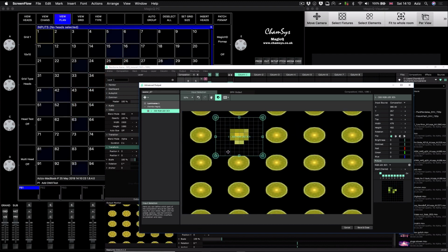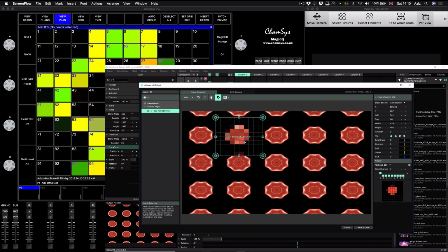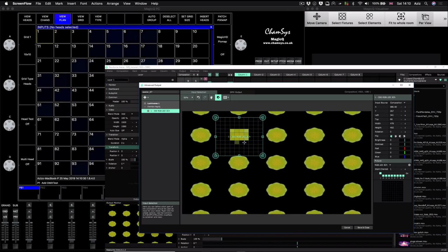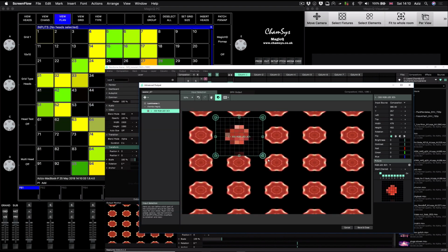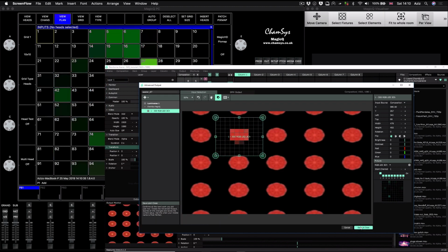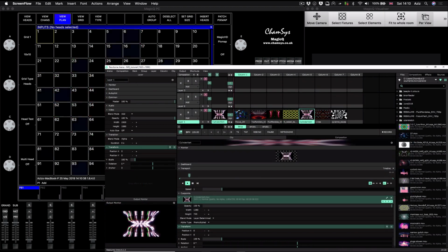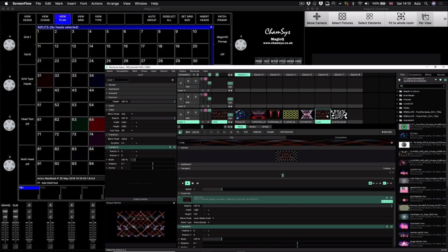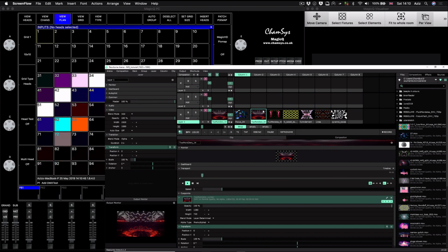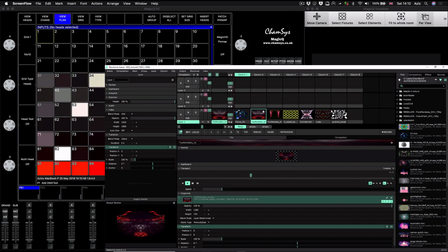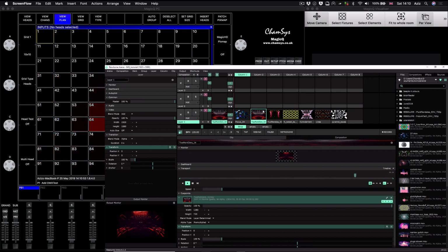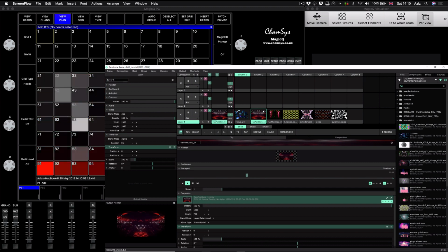the mapping area. As soon as you reduce it, and you look at your pixel mapping in Resolume, you can see it makes much more sense, and the pixel mapping is working perfectly. Then you can close it, and if you want to change the pixel mapping, you can change this, and now you're going to see a different pixel mapping running on the screen. Again, you can play with this and map stuff around. For this small amount of fixtures, that may not be the best example, but I just wanted to give you the direction of where to look.